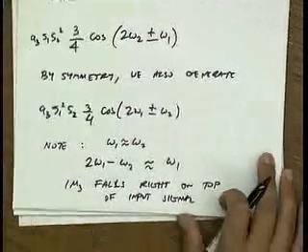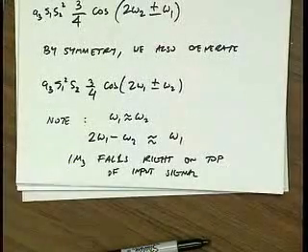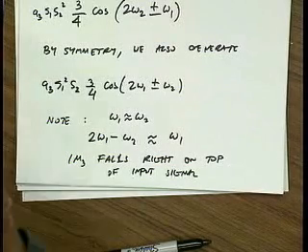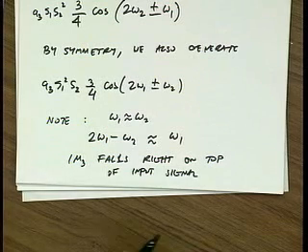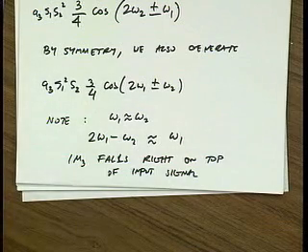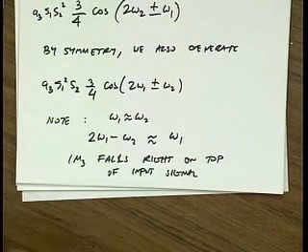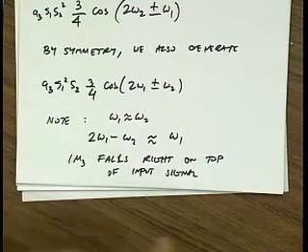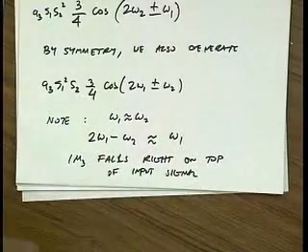In other words, before we had to dream up these weird scenarios where there were these two signals and they were just spaced right and they intermodulated and then they produced distortion, right? That hurt us. Here, we don't have to be very creative, right? The signal is going to interfere with itself. You might say, well, that still requires two tones, but really any modulated signal has infinite number of tones in it. So if I have a modulated waveform and it goes through nonlinearity, the third order intermodulation distortion is going to produce frequency right in band. So I'm going to create a signal that competes with itself.